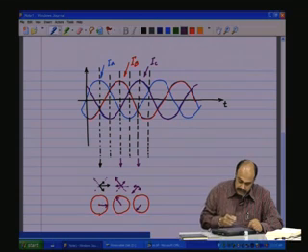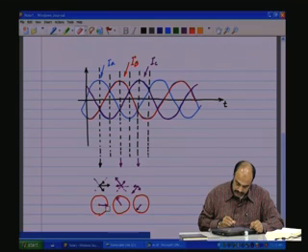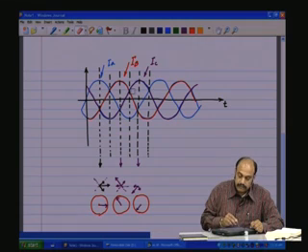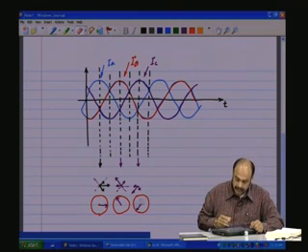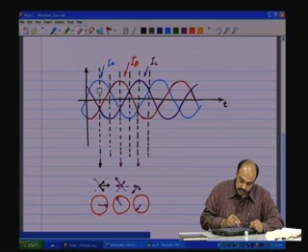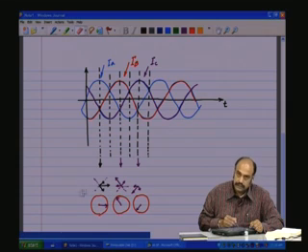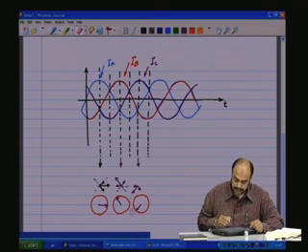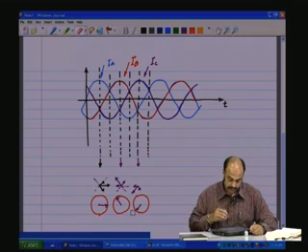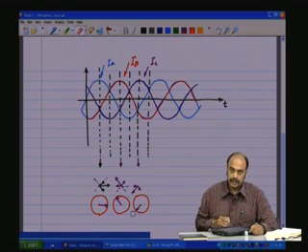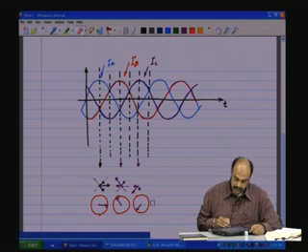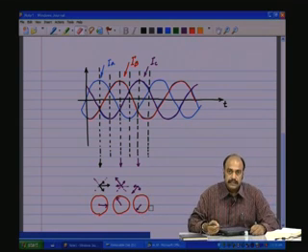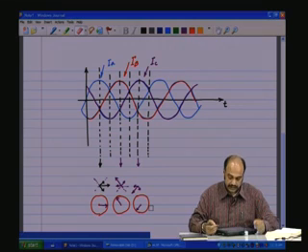So you see that the resultant flux, as time progresses, was in this direction, then it has rotated in that direction. We have taken some crucial points in between to show that the flux positions are changing. If we smoothly go along the time, you will see a smooth rotation along this circle, and then you will see that the rotating magnetic field has been created. So this vector which we are seeing here is rotating smoothly around the circle, and that is the rotating magnetic field.